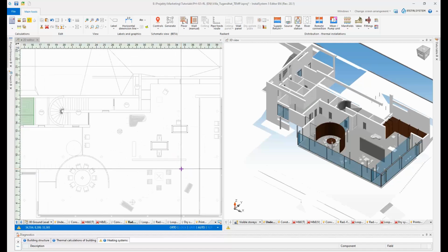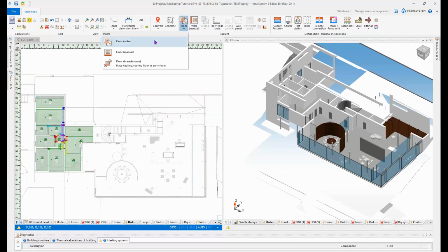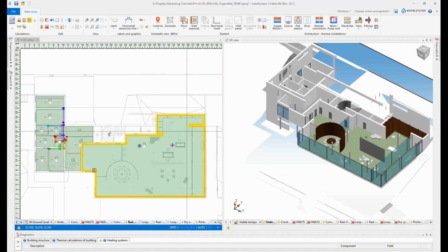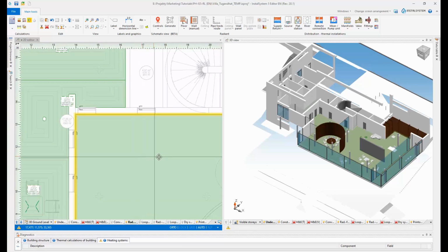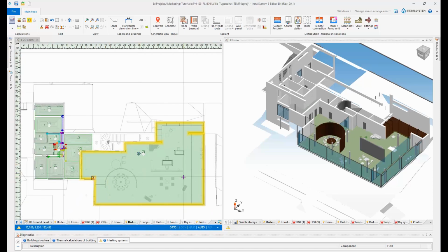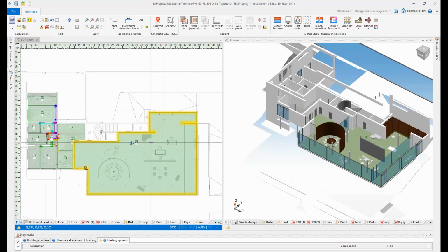As usual, first we need to put the heating zone. And that big zone must be first pre-divided. As you can see, for example, here in this zone, program can divide zone, but only in one direction. So in case of such big spaces, we need to first pre-divide the zone, make some smaller parts, smaller zones, and then we may let program to make further divisions into circuits.